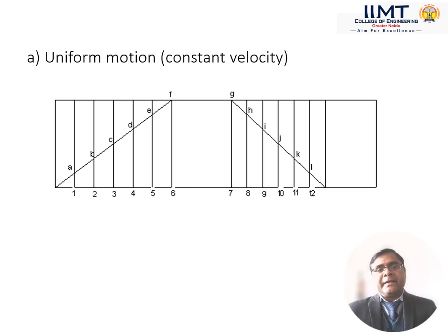Due to the straight line curve, a jerk is produced at the beginning and the last moment of the follower displacement. So this type of follower motion program is not used in high speed.